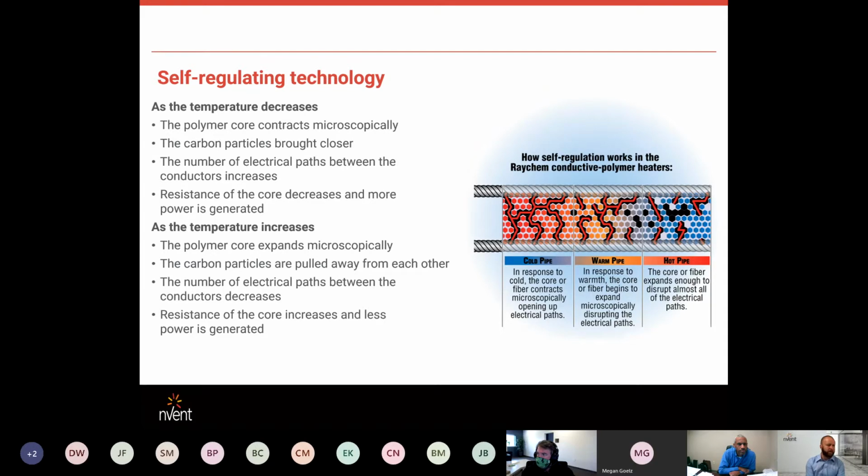If you sliced open one of our cables, you pull away a couple of outer jackets, a metal sheath, and some layers. Those layers are strictly for electrical and mechanical protection, not really the function or the action of the self-regulating cable. What the self-regulating cable is really about, in this diagram, you'll see 2 current carrying conductors going down the length of that cable. The first thing I like to explain is that those current carrying conductors are not heating elements. They are strictly delivering electricity, power, energy to the heating element, which is all along the length of the cable. So they are not heaters.